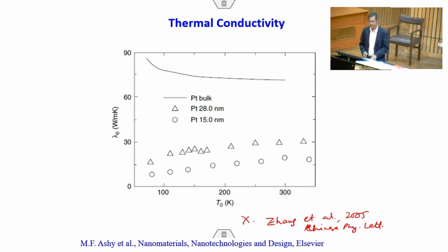That's very simple. As the thickness decreases, the energy levels are getting confined, and platinum is a metal, so the majority transport will happen by electrons. Therefore, electron energy levels get confined in the thickness direction, and electrons cannot easily move. Not only that, the moment you create thin films, you have a large number of nanocrystalline or microcrystalline grains compared to the bulk, and these grains will have grain boundaries. The grain boundaries will act as a scattering agent for the electrons. That means they will not be allowing the electrons to have a smooth passage. They will be acting as a scatterer.